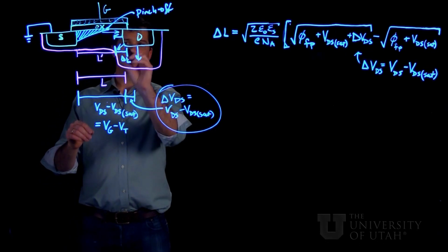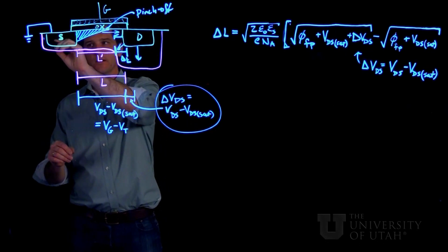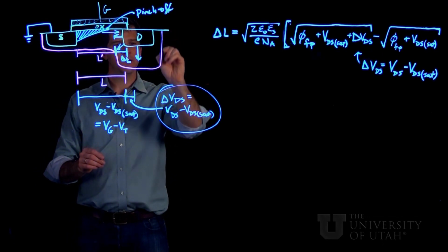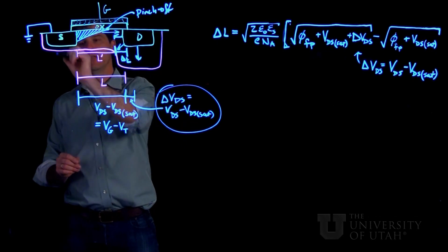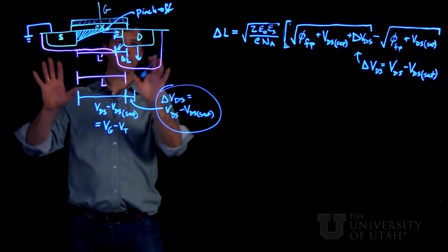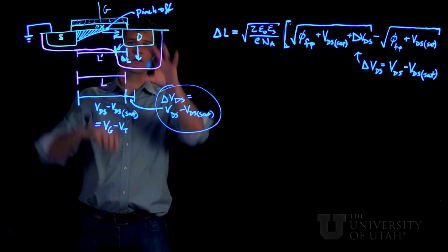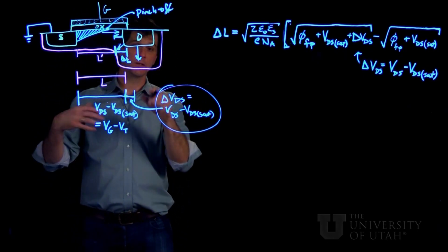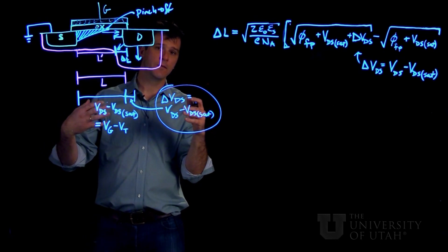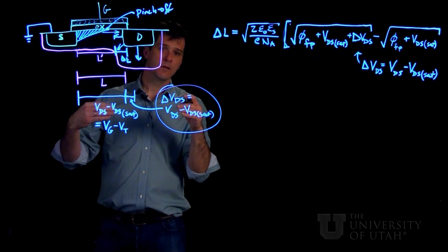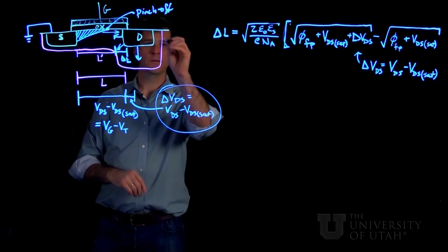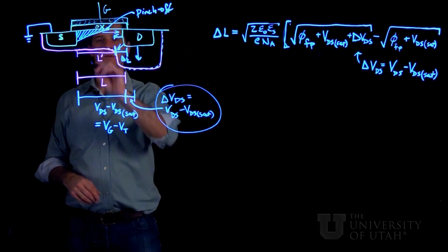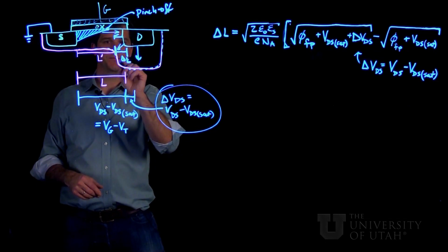Now also, because the drain's band diagram can kind of be thought of as being given by this equipotential line. So I've superimposed the voltages from the gate and the drain, and I've drawn a line of equal potential, which is defined by the depletion widths emanating from all of them. So this would actually be a reasonable picture of the band diagram itself.